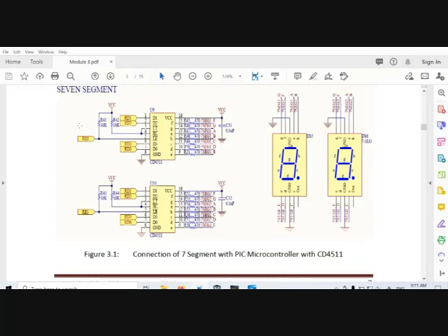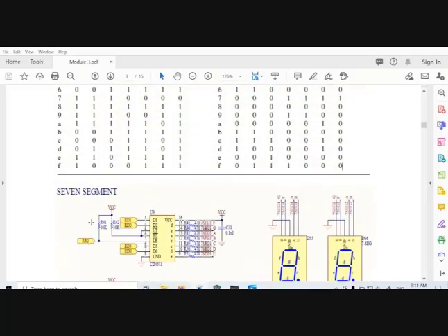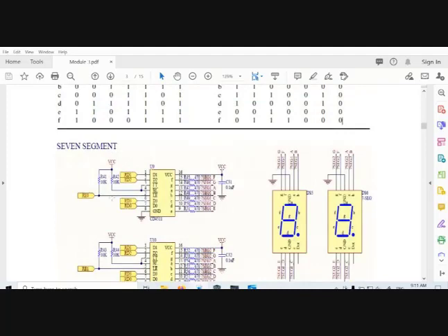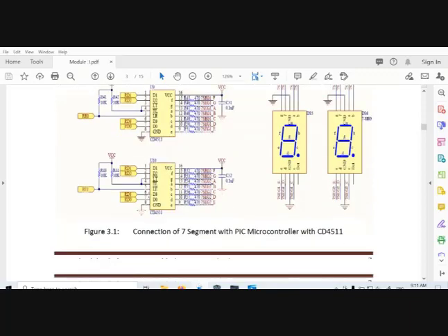So basically we use these pins, RE0 and RE1. We want to select which segment needs to turn on, either one or both. So you can do that through these two pins here, the select pins, which are connected to the LE. We call it latch enable.